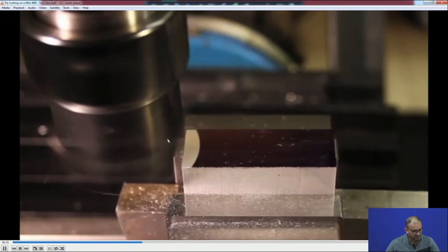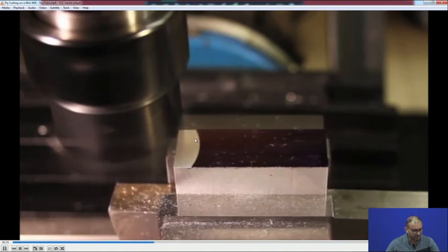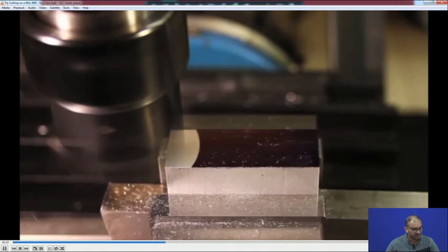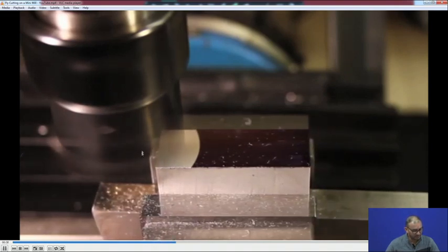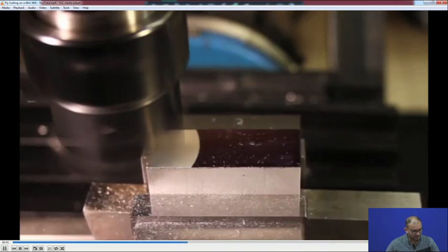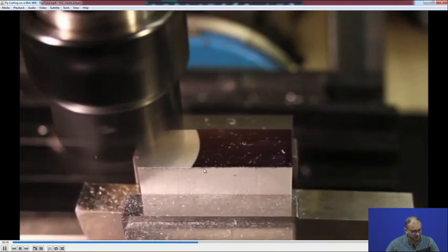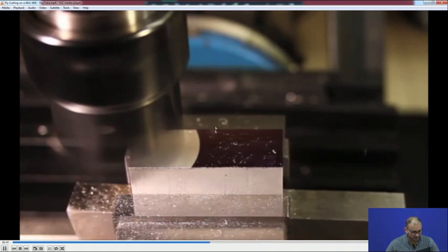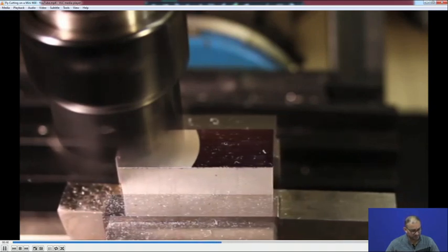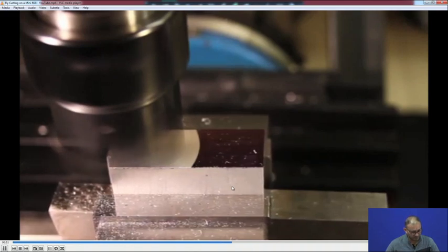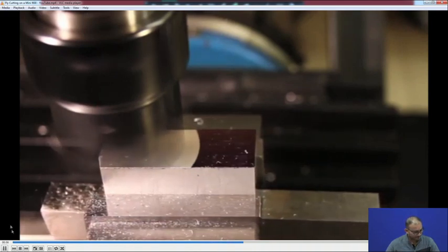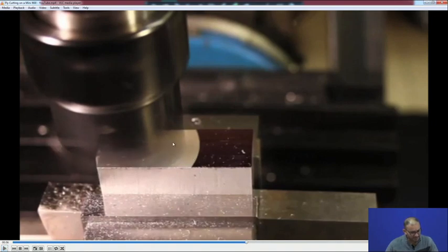So, what is the advantage of this? Here, you can do material removal on a very large surface, depending on the working area of this particular fly cutting tool. If it is larger, you can get even tens of centimeters of workpiece cut in a single pass. No need to do multiple passes for machining of those components. And another thing is the curvature. If you put this cutting tool on a horizontal axis, then whatever this curvature is, you can create a concave surface on any circular or non-circular component.